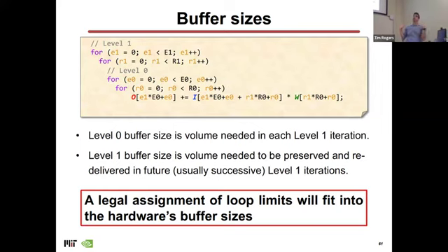Okay. When you do tiling in CPUs in x86 programs or in C++ or whatever, you're just relying on the fact that you have a cache underneath. This is explicit. This is saying I'm loading this stuff into the buffer. I cannot overfill the buffer, so I have to make sure that all of my loop bounds fit inside the buffers I know I have on my machine. And as a result, you can make significantly more efficient hardware, at the cost of programmability. And DNN accelerators usually opt for this because the computation is just so regular.